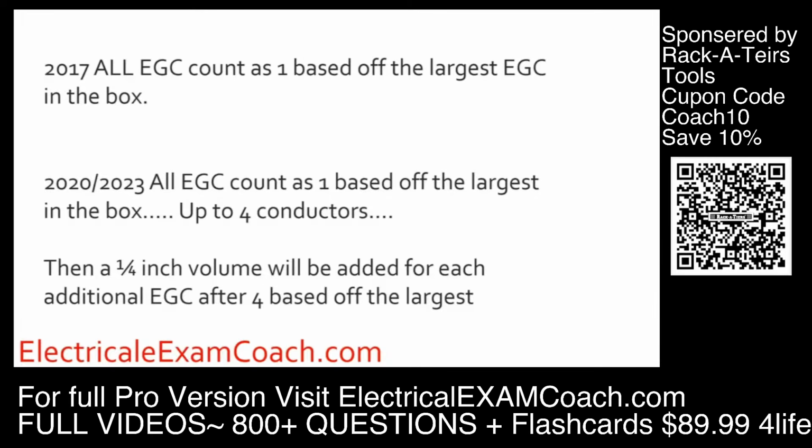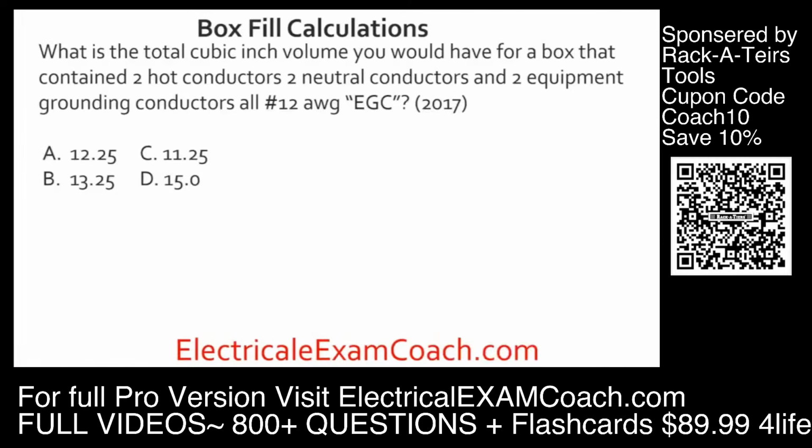I'm going to teach you how to do it one step at a time. What is the total cubic inch volume you would have for a box that contained 2 hots, 2 neutrals, and 2 equipment grounding conductors, all of the 12-gauge persuasion in the 2017?